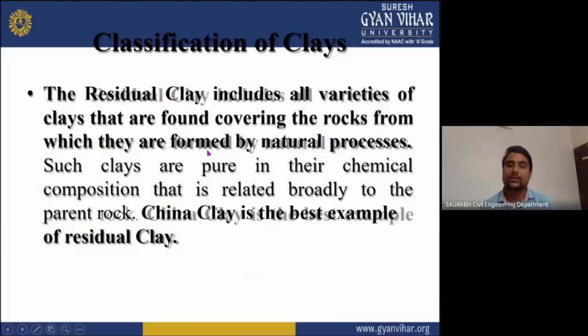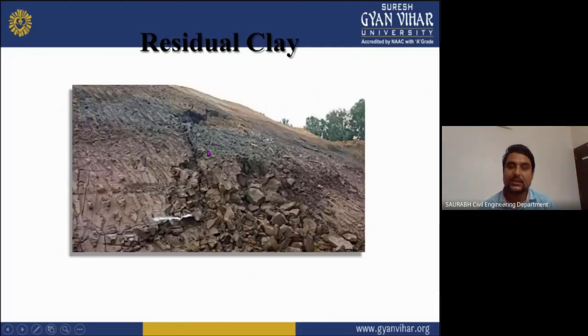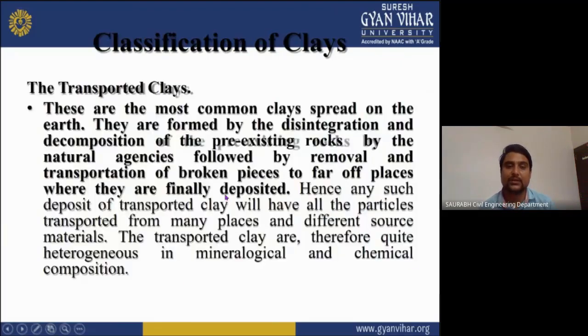Such clay is pure in its chemical composition, which is related broadly to the parent rock. China clay is the best example of residual clay. If you look at your home, there are many crockeries, and these crockeries are made of China clay. Now you can see the photograph of residual clay. This is deposited on the surface of the earth.